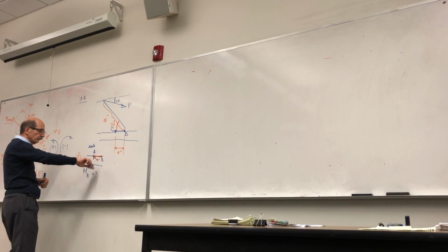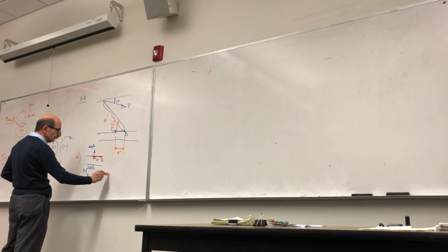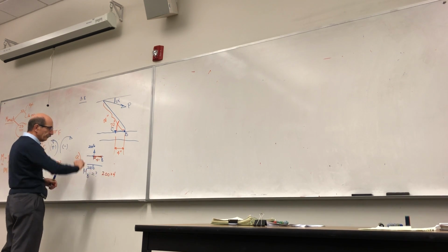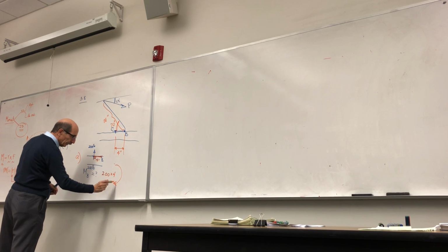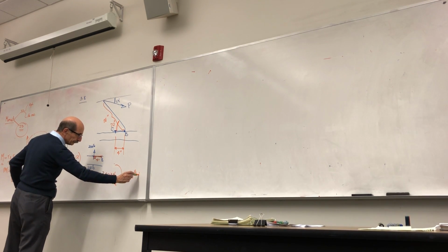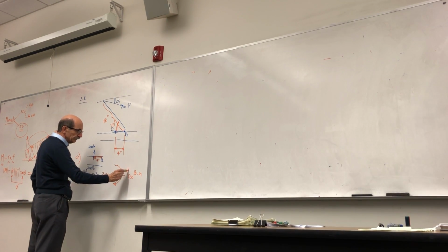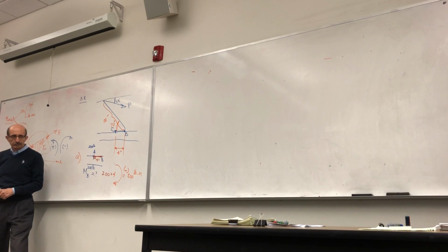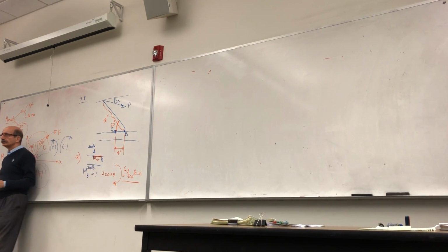So in this case, the moment that would be generated, its magnitude is 200 times 4, but will be clockwise, or like this. So it would be 800 pound inch clockwise or negative. Either one is the same. Okay? Any questions?